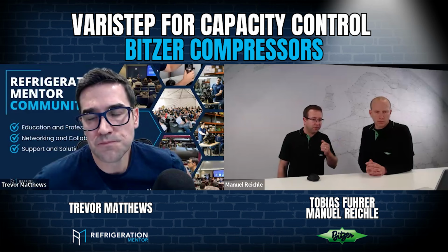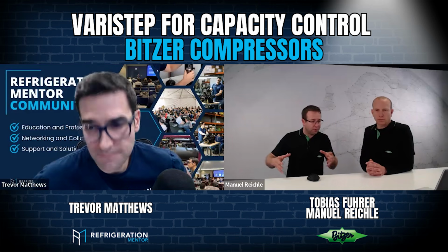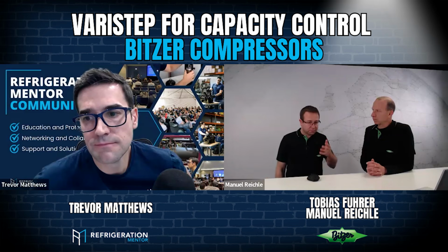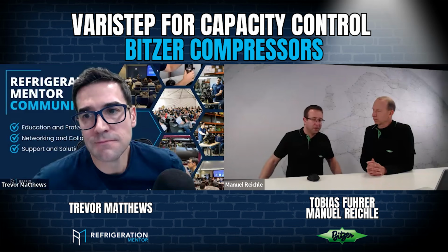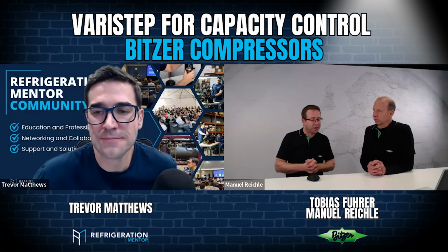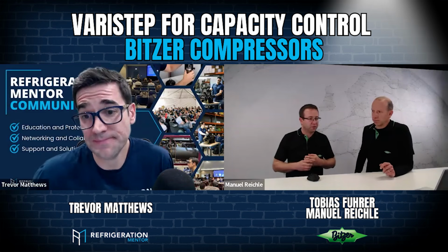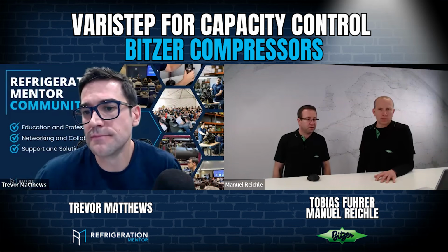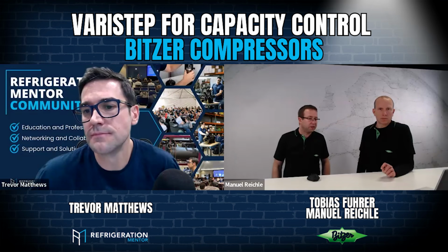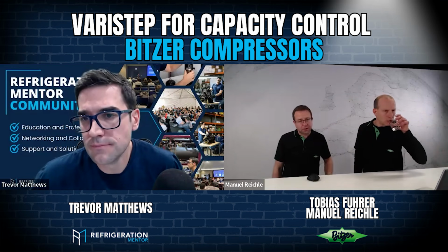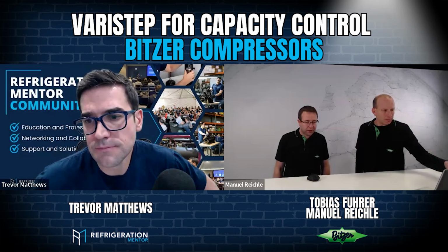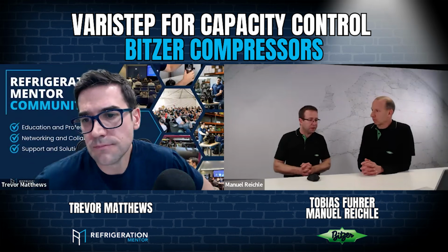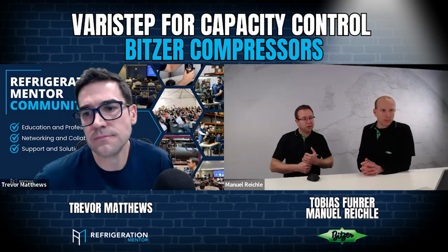But if you have a compact chiller, let's say with a braze plate heat exchanger directly after the compressor with a couple of inches of suction line, then stopping and starting the mass flow is not the best idea. So for the 2 cylinders and the smaller capacities, we always try to get in contact with our customers, but it's possible. On subcritical, we get requests here and there, and we look into that together with our OEM customers to offer a solution in the future.